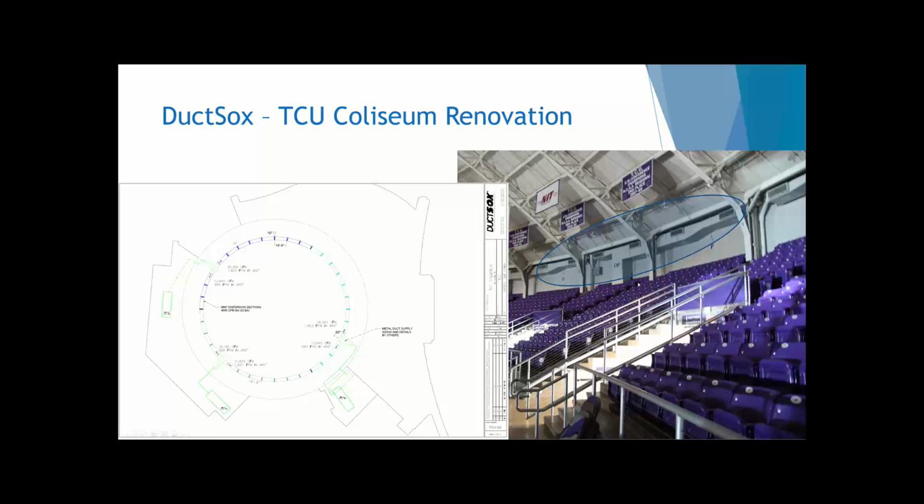It would condition the space. It would mix the space relatively well. But notice how it's throwing above the occupants. It's throwing into the middle. So they do end up getting mixed air, but it's not as efficient as the design that DuctSox came up with, which they ended up putting